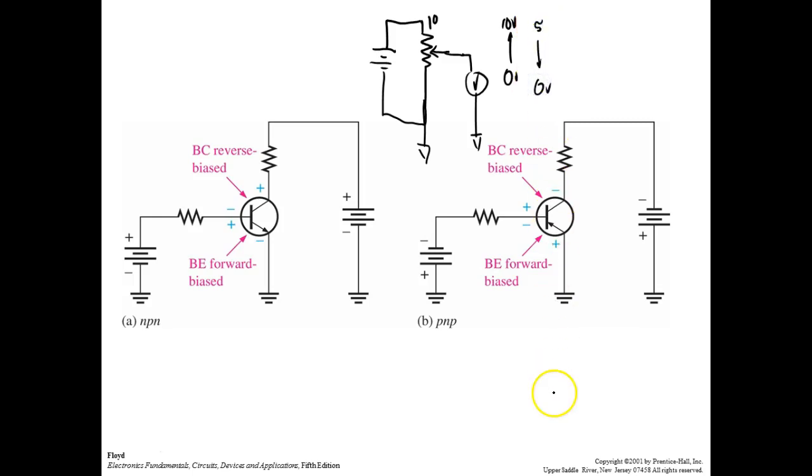0. Well, if I come over here and have a rheostat, and it's a 10K rheostat, then I can adjust this resistance. So if this is a 10K pot, it'll always be a 10K pot between those two leads. So the resistance between pin 1 and pin 3 doesn't change. Y'all understand that? Unless I hook something in parallel. Over here, if I start adjusting this, it will adjust anywhere from 10K down to 0 ohms or 0K.